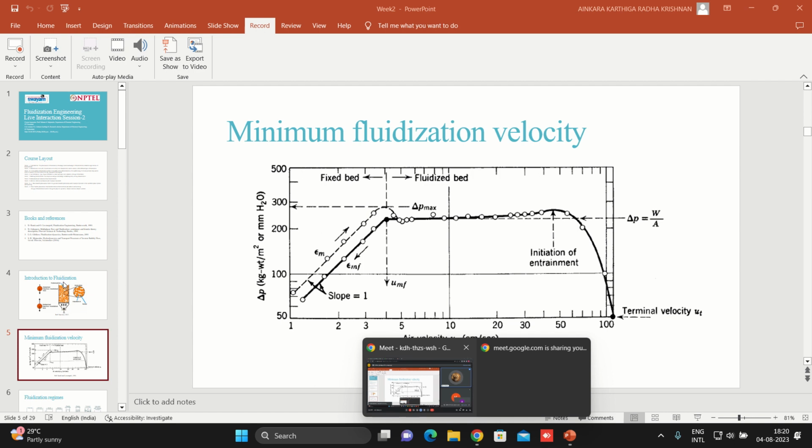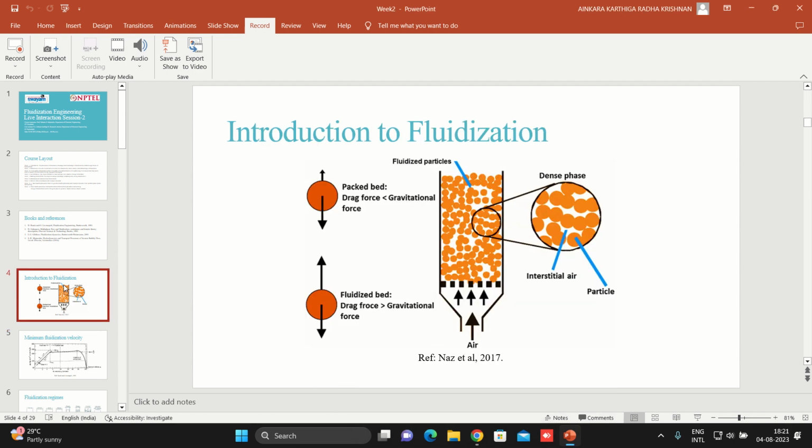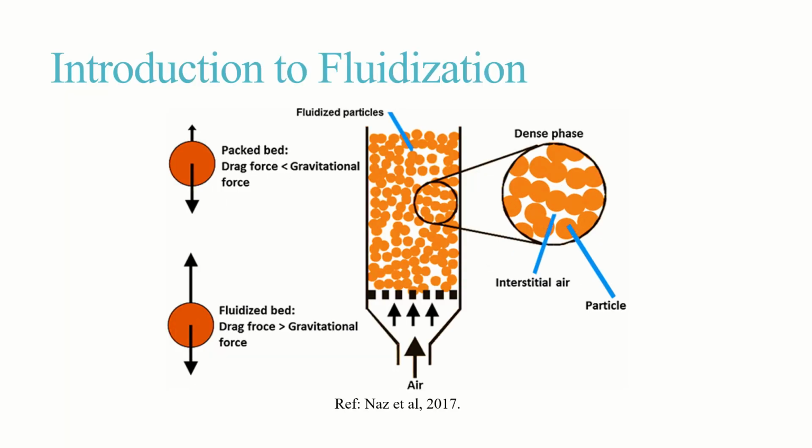A couple of limitations with fluidized bed, right? Can you use gel-based packing in order to avoid things like attrition? It depends on the particles, right? What do you mean by gel-based? Say you're using a catalyst, a nano catalyst, whatever. You can disperse it in a gel, make it in the form of spheres or whatever packing, so that with the property of gel, attrition is minimum, and the disadvantages are overlooked.